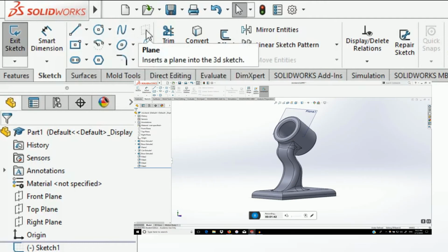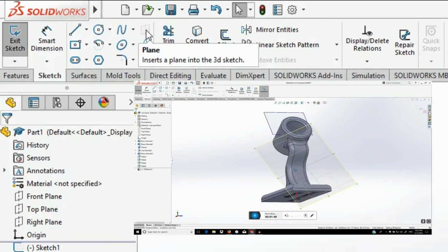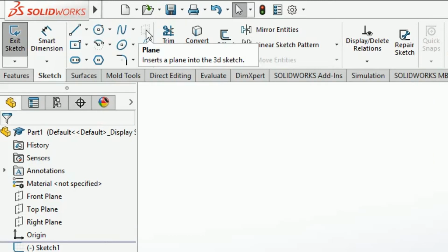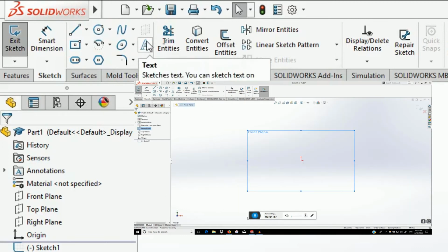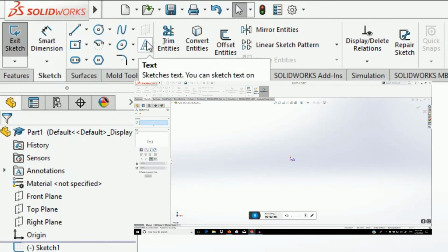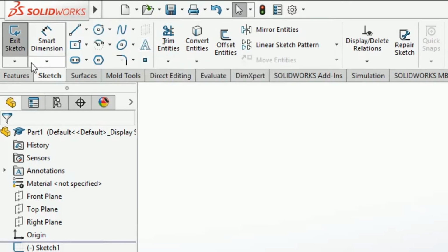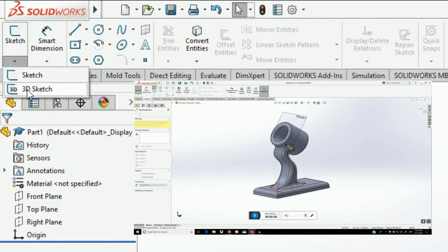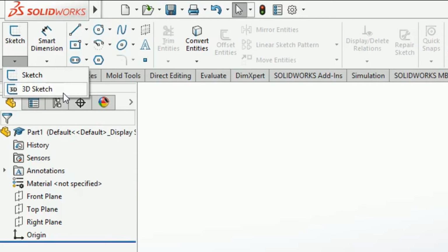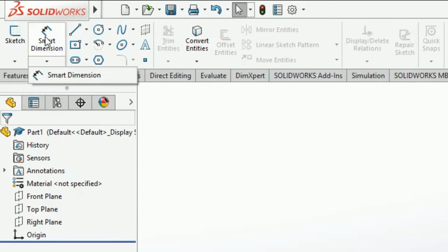Sketch planes create planes that can only be used to sketch on and hide with the sketch. To define one, you need 3 points, a point and a line, or another plane or object side. You can also add a lonely point. You can also add lettering on the sketch, and choose the font and size, among other things. Concerning the things we said in the beginning, you can also sketch without choosing a plane, but choosing a 3D sketch. It is mostly used to join edges or features together fast and is not used for brand new sketches.